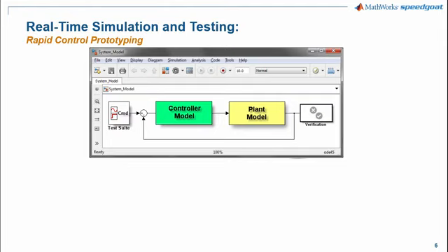The goal is to run the Simulink controller algorithm design shown here as the green subsystem on the real-time target computer hardware interface to the actual plant hardware. Right now you can see that it is connected to the plant model, or in other words, the model of the thing we want to exercise control over, shown here as the yellow subsystem. This entire model was used to initially design the controller through the use of simulations in Simulink, but now we're ready to start doing rapid control prototyping. To implement this with Simulink is quite straightforward.